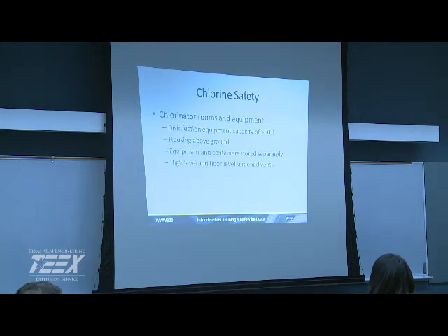Got to have proper ventilation. Even if you're using bleach, it's good to make sure whatever area you're feeding in is well ventilated. And with gas especially, you want to force air in from the top and then let it escape out the bottom because it's going to push the chlorine gas out. Normally, especially with chlorine gas, you're going to have it separated. Got to keep it up at temperature properly.